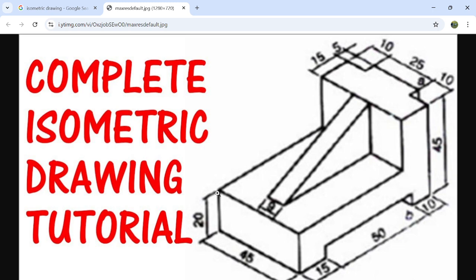If I want to draw only this rectangle, and then draw another rectangle to create that shape, then you have to use the XY plane. But the basic method of good design is that you sketch your model in a way that requires minimum sketches and minimum commands. That is the best way of any design.